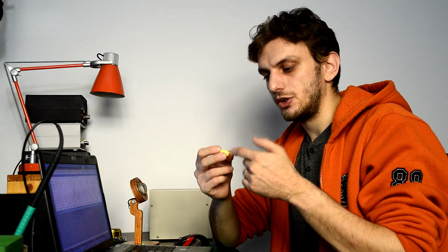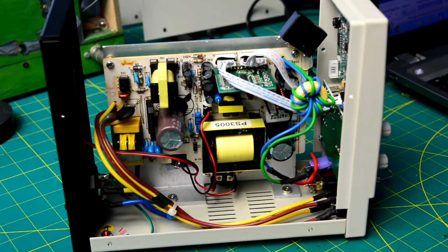Now if you don't have this sort of thing, you can simply use a ferrite ring. This again can be found in all sorts of circuits. Usually there's a bit of wire around it, but you can simply take the wiring from your supply and thread it through this thing. The more times you thread it, the more inductance you're getting. And this way you can increase the inductance of the wires and create a better filter. So that's the theory. Let's see how this actually works in real life.